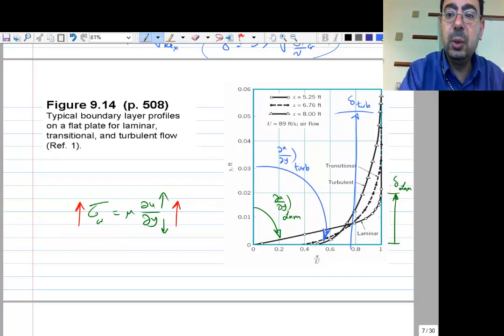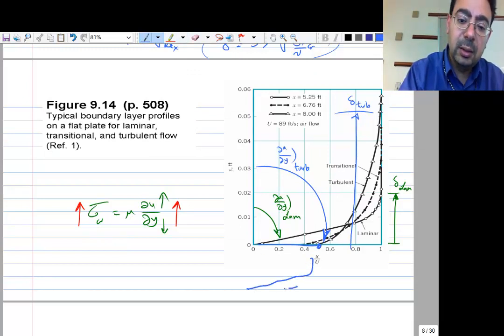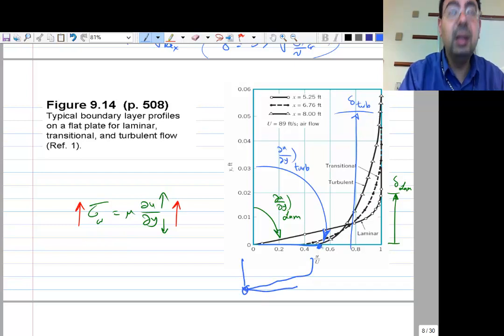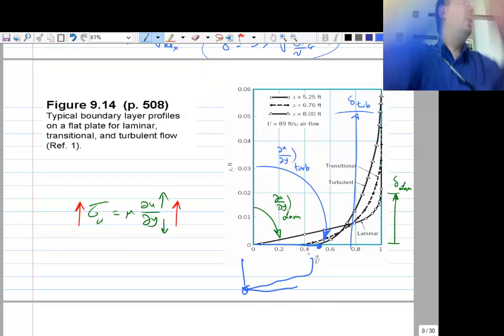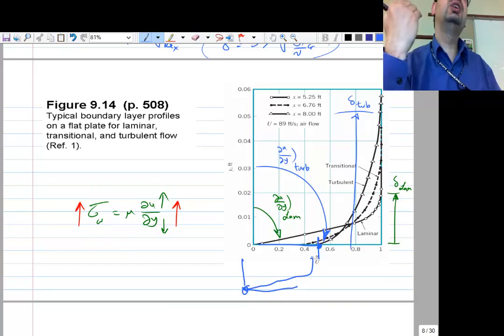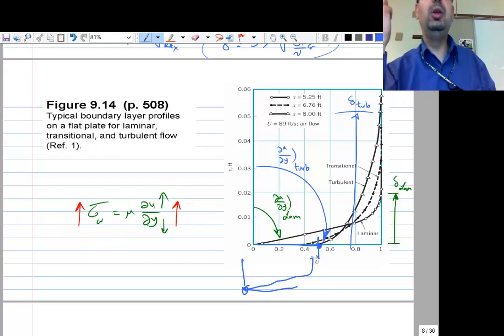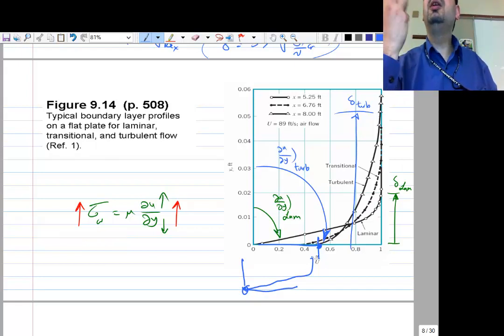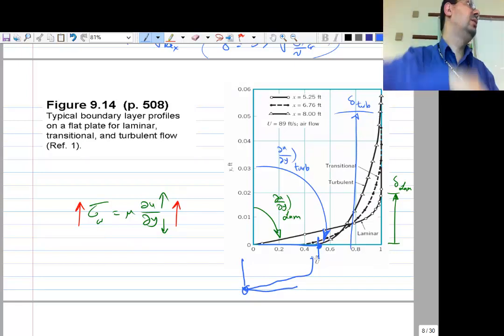To the extent that it looks as if there is actually velocity at the wall, but no, it's still zero. It's just trying to show you that it feels as if the turbulent boundary layer brings a very high velocity all the way down to the wall. That's how strong the velocity is near the wall for a turbulent flow. So that, of course, creates huge drag, right? When you look at it, it's as if the turbulent flow has increased the connection between the layers and each other.